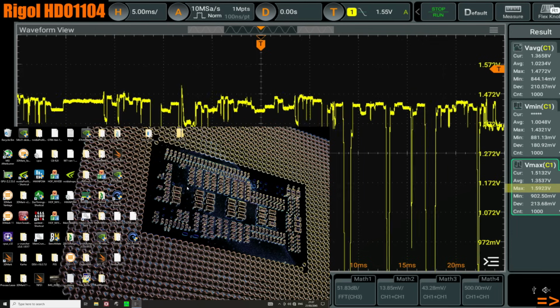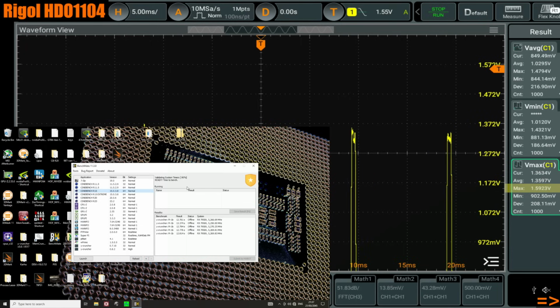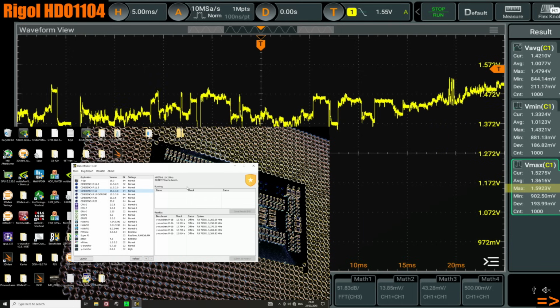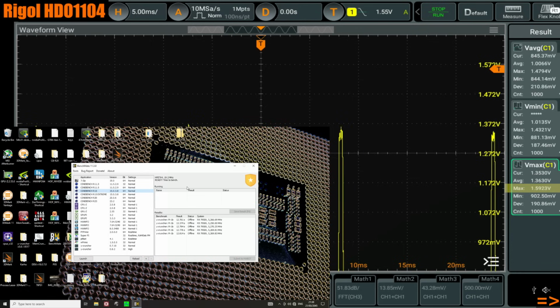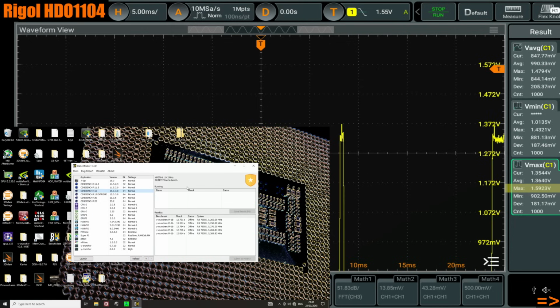Anyway, we're not going to get into that, but I kind of suspect that really high voltage spike when Windows is starting is some kind of issue with the voltage regulator's control loop on this motherboard. This behavior might be present on some other boards. I'd imagine it's probably present on every MSI motherboard that uses this VRM, but there are a lot of MSI motherboards that don't use this same voltage controller, and those probably don't do this. But anyway, that's the first concerning thing with this motherboard.